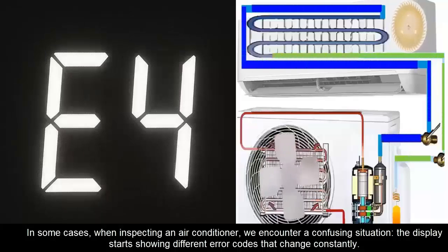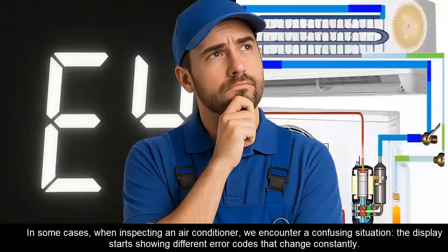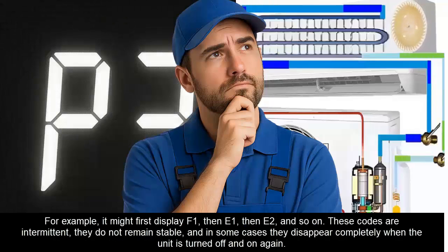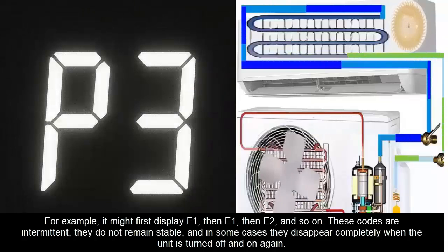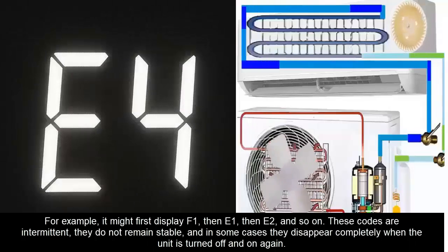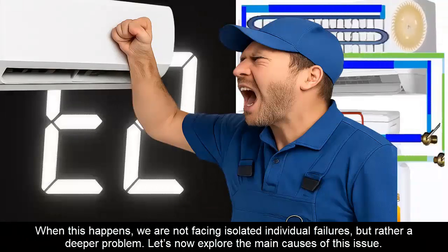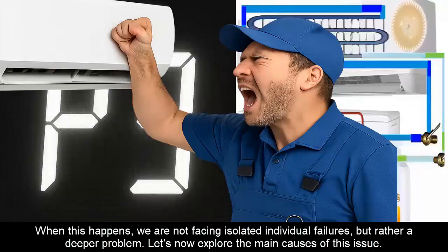In some cases, when inspecting an air conditioner, we encounter a confusing situation. The display starts showing different error codes that change constantly. For example, it might first display F1, then E1, then E2, and so on. These codes are intermittent. They do not remain stable, and in some cases, they disappear completely when the unit is turned off and on again. When this happens, we are not facing isolated individual failures, but rather a deeper problem.